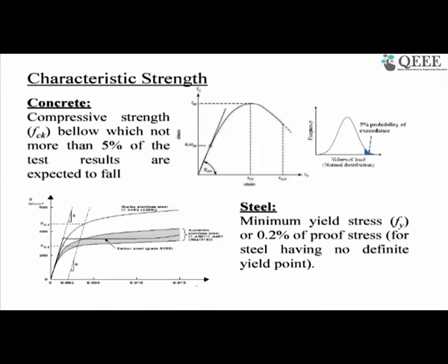We have discussed load. We need to design the structure such that whatever load comes on the structure, it can resist it. So naturally, we need to discuss the strength of the structure. Again, strength of the structure is also probabilistic in nature, because suppose you are making concrete. I believe that all of you, if you had a concrete lab, mix several ingredients together to get a concrete mix. Now, when we mix them, at every stage, when we procure material, we weigh them, we mix them, we contribute some amount of variation. Therefore, finally, if you test 100 cubes, 100 concrete specimens, it's not that 100 times you will get the same result. There will be some statistical variation in the result.